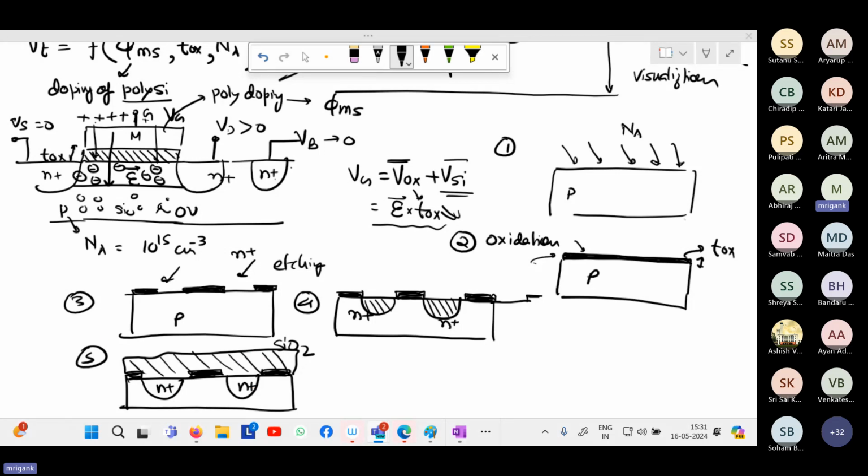And then actually these are acting like wires, but ultimately these are like metal layers. And this is like the via. We call this term as via. Via means it is connecting, say this is the metal one layer. This is the metal one layer M1, and M1 is connecting with the source drain region and the gate region using these vias. Vias run vertically in the field oxide. So overall, this is the process roughly for the fabrication of MOSFET.